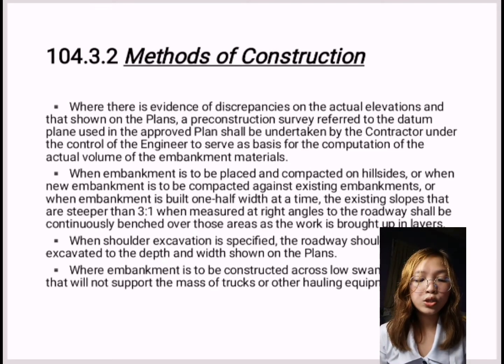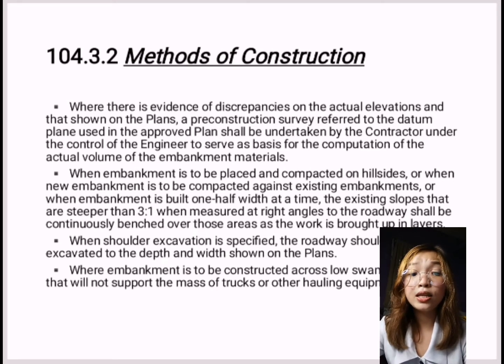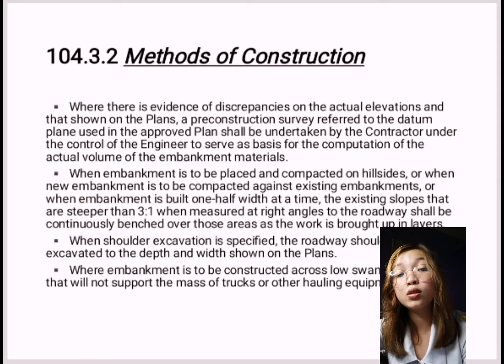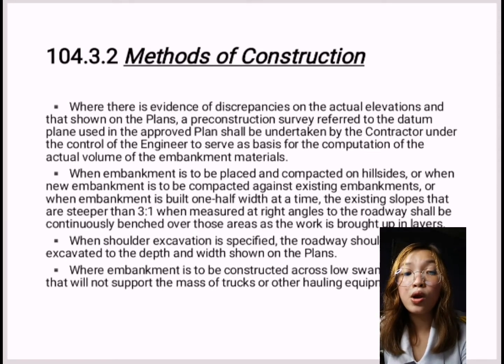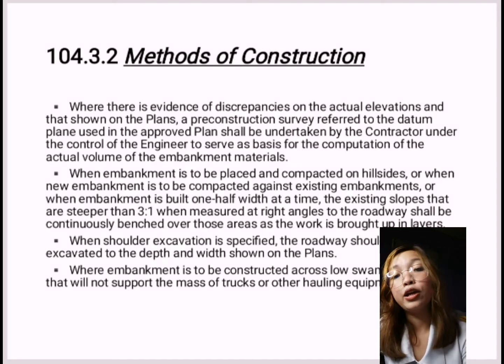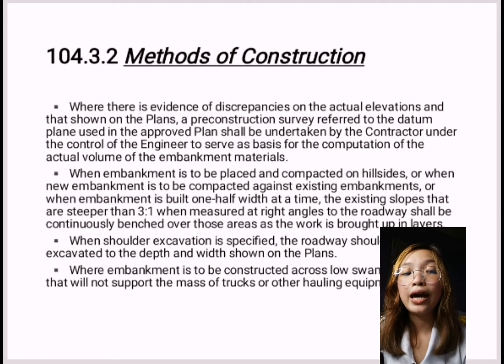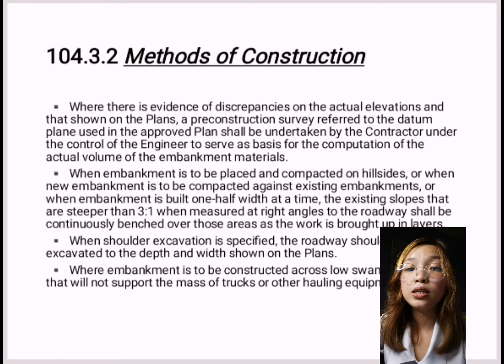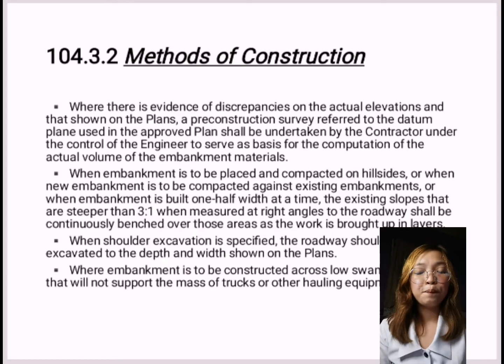So now let's proceed to the next, where embankment is to be constructed across low swampy grounds that will not support the mass of trucks or other hauling equipment. The lower part of the fill may be constructed by dumping successive loads in uniformly distributed layers of thickness not greater than necessary to support the hauling equipment while placing subsequent layers.